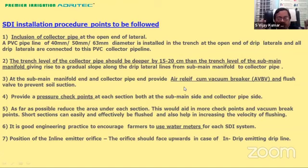And also, when we do the designing of the system, as far as possible, try to keep shorter sections so that we will have efficient flushing and the water will keep getting circulated. The most important thing over here is to encourage the farmers to use water meters, because if there is a drop in the flow or a drop in pressure, then immediately we will come to know that there is some problem with the system lying underneath the soil, which is not physically visible to us. And in the case of an inline emitter system, if you are having the flat emitter system, the orifice typically should be facing the top and not the other way around, so that we avoid the roots searching and coming into the inlet of the emitter.